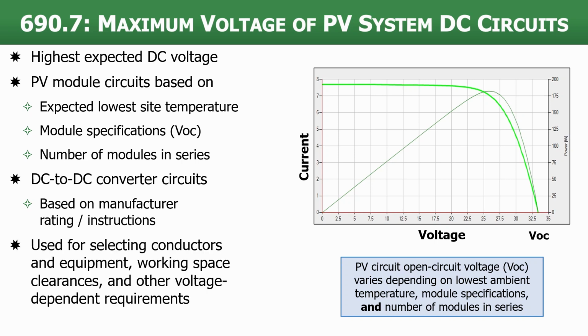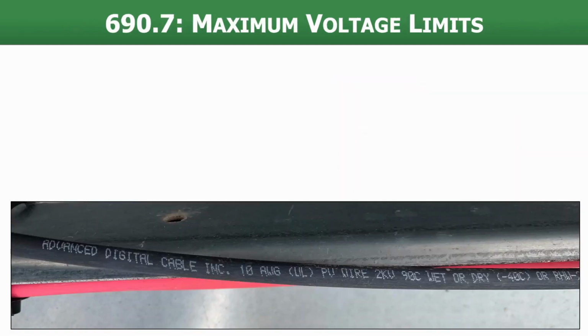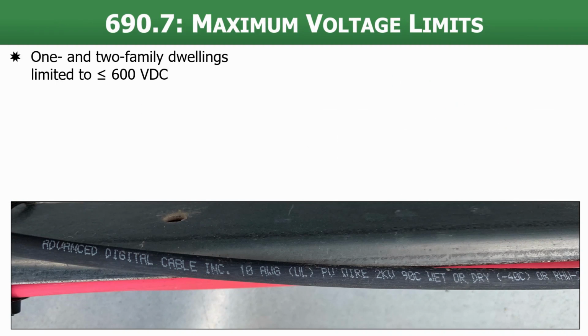Now, why do we calculate maximum voltage? Well, we need to know the maximum voltage of the system because we're going to be choosing different types of conductors, all the equipment. There's also working space clearances and other voltage dependent requirements within the National Electrical Code that depend on the maximum voltage of a system. Section 690.7 provides us with some guidance for our maximum voltage limits.